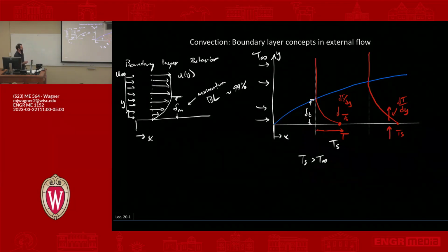Laminar flow is a flow condition where there's no velocity component in the y direction. So maybe it's important to say that: u sub x is not equal to 0, and u sub y is equal to 0 for this case, for laminar flow. If you look at the word laminar, whether it's Latin or Greek, it actually means sheets, like laminations. So you have these sheets of fluid that are just sliding over each other. There's no velocity component in the transverse direction. Because it's laminar flow, it behaves in this consistent way. So this is the conceptual stuff that we need to know for laminar flow.